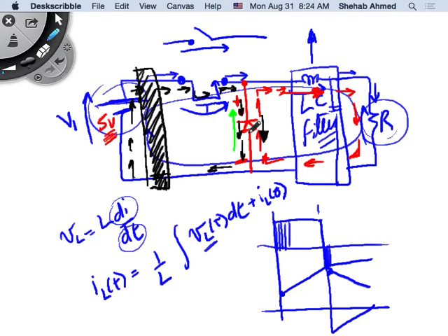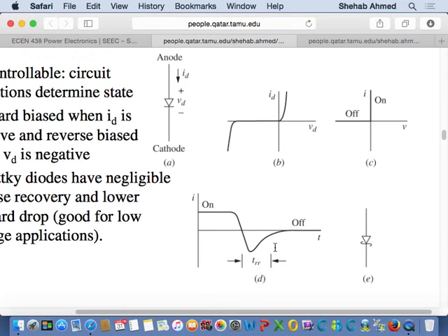But now, after this short period of reverse recovery, so it's called reverse recovery time, now the diode blocks. If the diode blocks, finished, the MOSFET is on, and we go back to the same thing. MOSFET is on, diode is off, current is flowing, MOSFET tries to turn off, the diode will pick up and conduct, because inductor current is continuous. Okay? And this reverse recovery time is a characteristic of the specific diode that you choose, right? So if this reverse recovery time is long, is that a good thing or a bad thing?